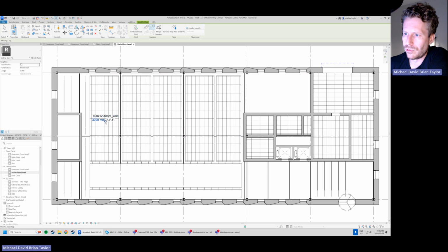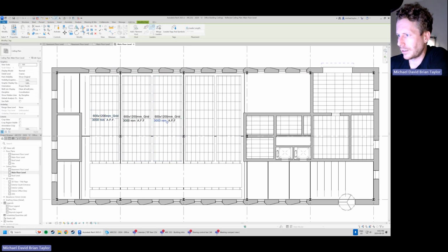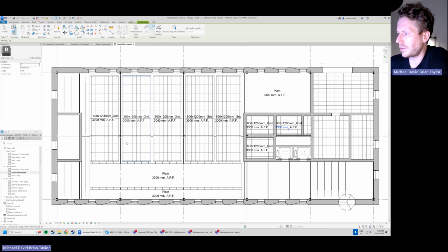A little move icon there. Click again. So every time I click, I'm generating the tag for my ceiling. So for us, you can see how quick this can happen, right? So annotations are a huge bonus inside of Revit to get these things up to speed pretty quick.